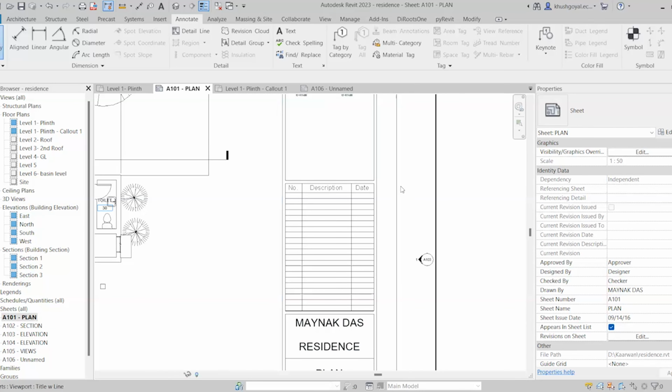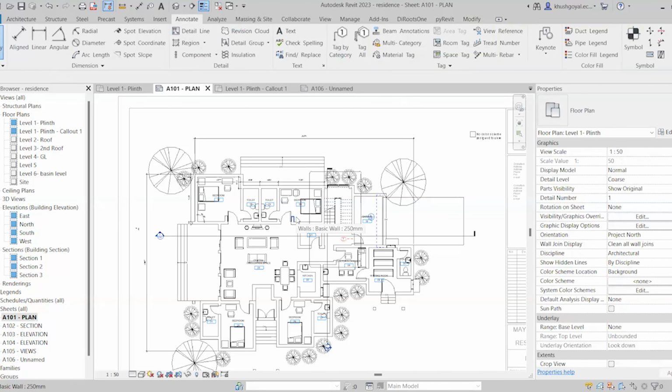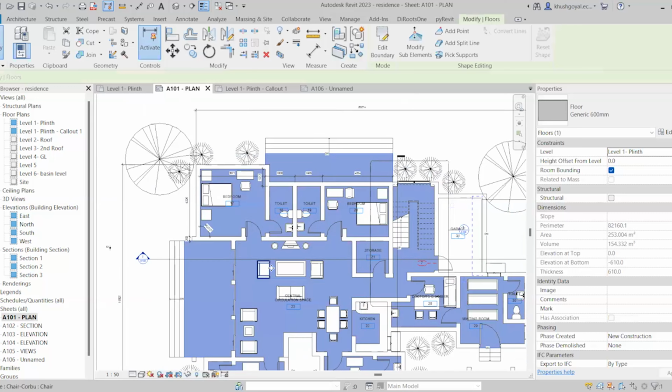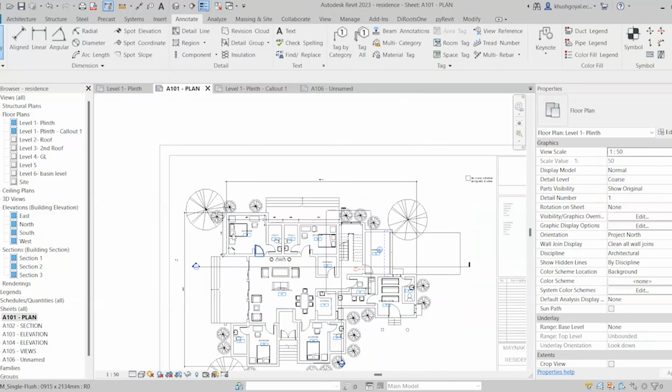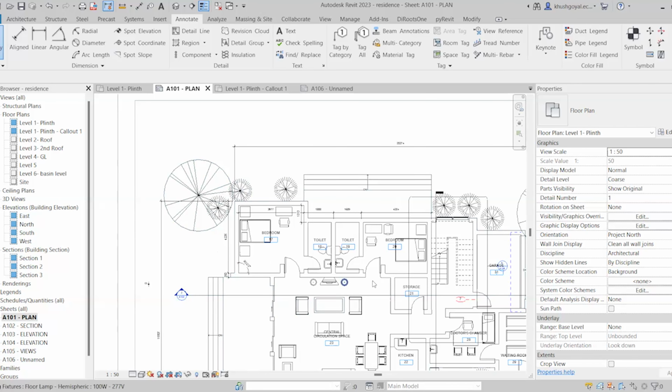In this, we give the serial numbers and we make the description revision 1 and we give the date to it. So wherever we are putting revisions, let's say I'll select this plan and I'll go to annotate tab. For example, I'm submitting this project to a client. This is my first revision which I'm giving to him, and in that I am revising this whole layout.